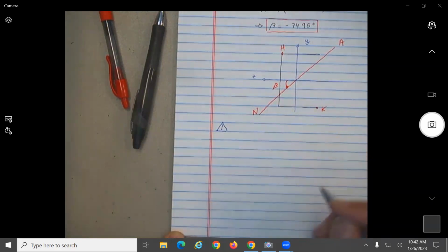What's important is what we just discussed: the location of the neutral axis depends on what? Does it depend on the geometry? Well, a little bit, but it also depends on the loading. So a cross section can have different neutral axes depending on how it is loaded, no? It's not like the CG, which is not going to change no matter what, no?